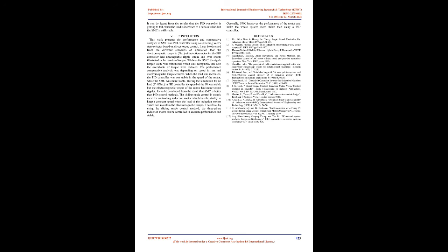When the load was increased, the PID controller was not stable in the speed of the motor, while the SMC was more stable. During the simulation for no load, T equals 0 N.m, with the PID controller the speed of the IM was stable but the electromagnetic torque of the motor had more torque ripples. It can be concluded from the results that SMC is better than PID control methods.